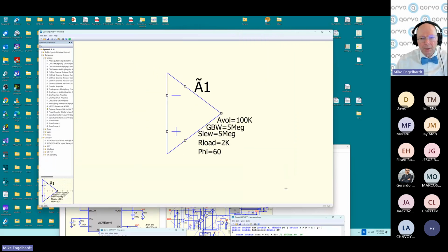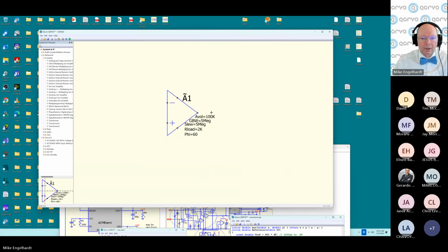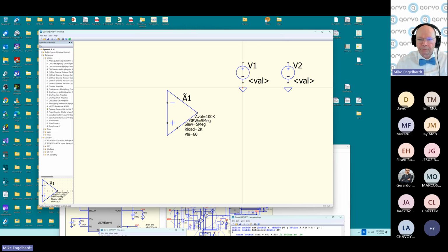Okay, so this is going to be a rail-to-rail op amp. The way a rail-to-rail op amp works is the output is a complementary common source or common emitter output. So the output is very high impedance, and it's locally regulated to look more like a voltage source with a capacitance from the very output node to an internal node, and it's a Miller multiplied capacitance that's the dominant pole and tames the output gain. That's the way they're implemented. So we have to power this thing. It won't run if you don't power it.